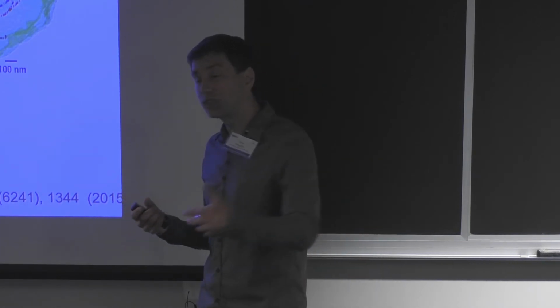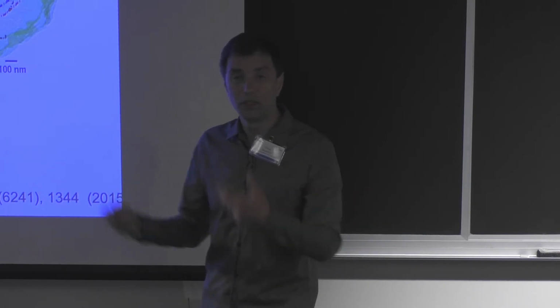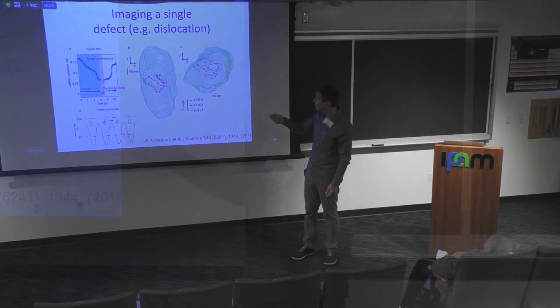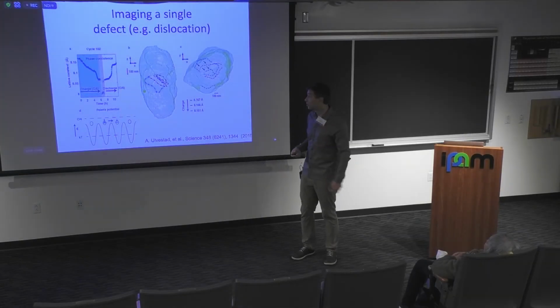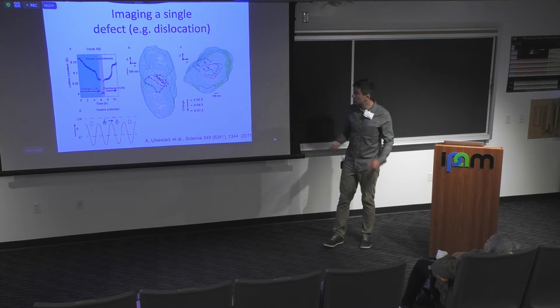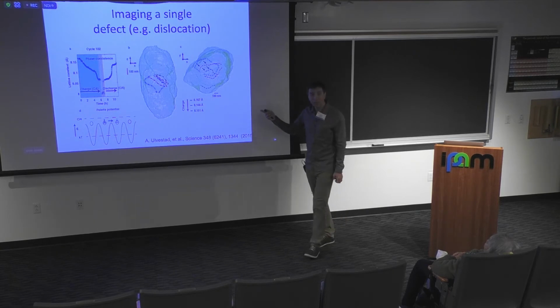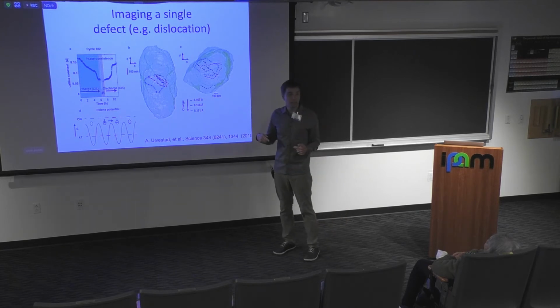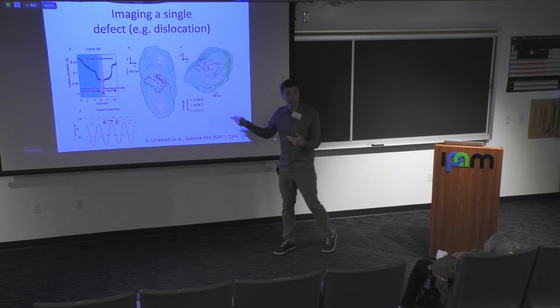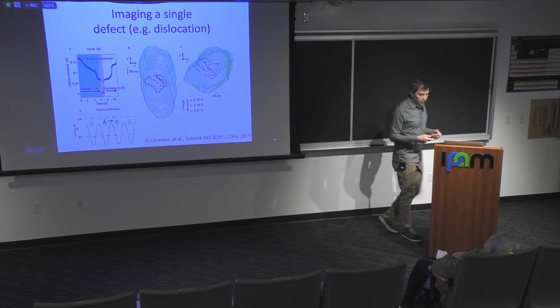But when you start passing currents, because they involve motion of the ions and redistribution of strains, they can move these dislocation lines around through the crystal. And we can visualize it as it happens, basically in real time, as we're going through the cycles of charge and discharge. To me, it's interesting from the perspective that we can control them by means other than temperature, right? We can perhaps even drive them with currents in specific directions in these materials, if we wanted to either drive them away or move them in a specific controlled way.